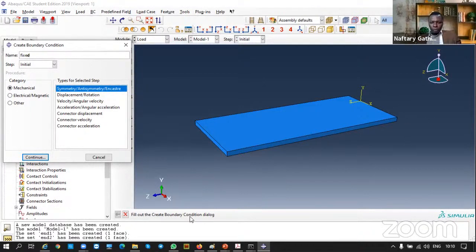So what we are doing is this is fixed. And then this is our plate there. I'm showing the thickness direction and then a load pulling there. So for you to understand clearly, usually the plate will be maybe in this direction, and then a load is applied here. So this is fixed. This is why I'm using this option, encastre or fixed edge.